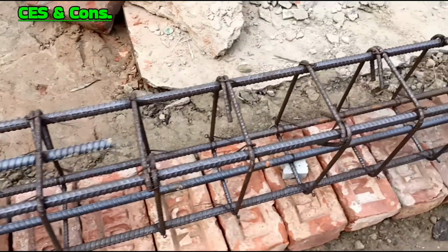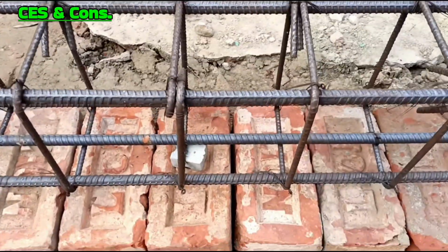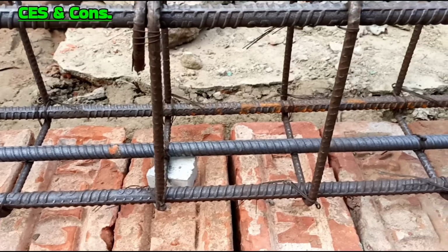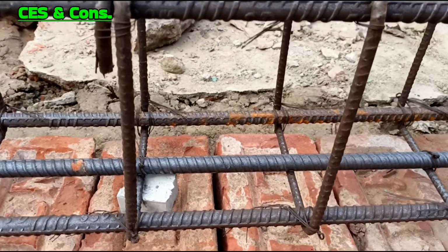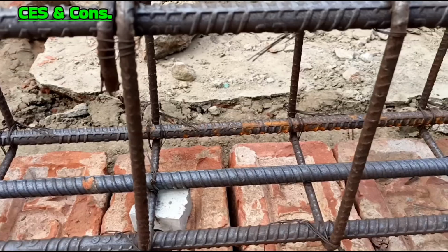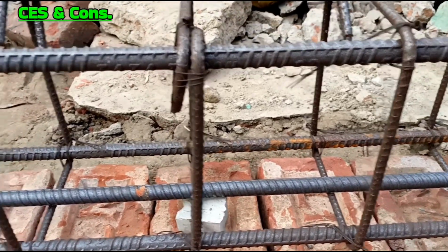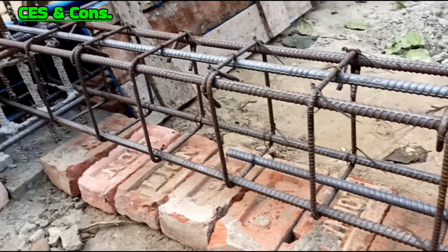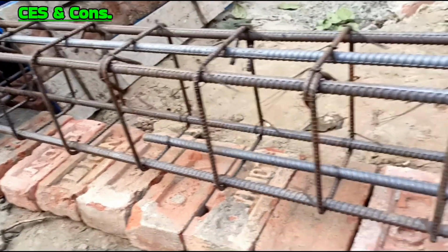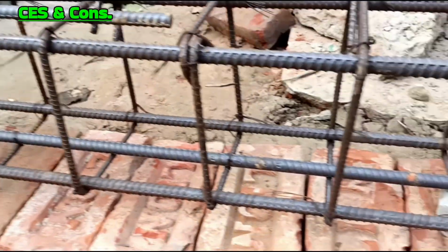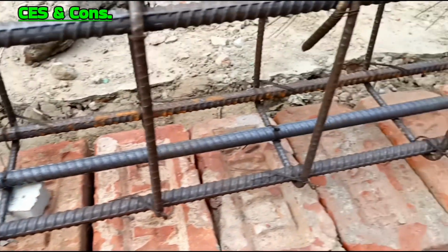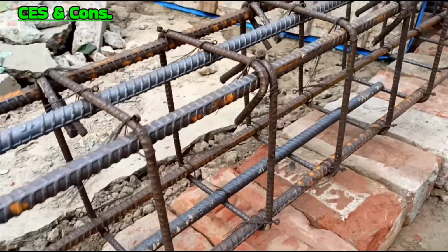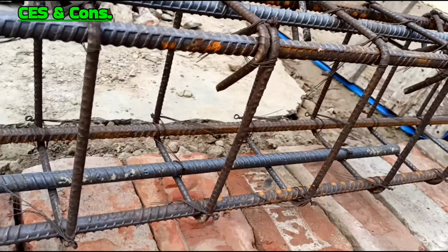Now friends, I am going to discuss the different components of the reinforcement of a plinth beam, including different stresses, moment and shear. In case of a simply supported or continuous plinth beam of a building, the maximum positive bending moment or sagging bending moment occurs at the midspan of the beam, and maximum negative bending moment or hogging bending moment occurs near the supports of the beam. It means the tensile stress occurs at the bottom of the beam and at top near the two supports, whereas compressive stress occurs at the top of the beam.